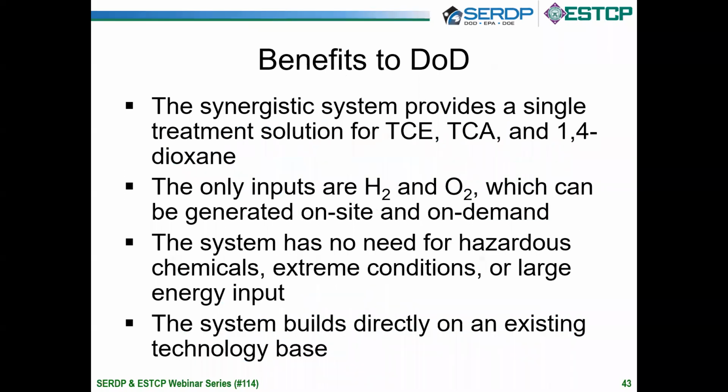So my last slide, benefits to DoD. Well, we have created a synergistic system. It allows us to have a single treatment system for TCE, TCA, and 1,4-dioxane. It's a simple system. The only inputs are hydrogen gas and oxygen gas, and they can be generated on site, say by electrolysis.